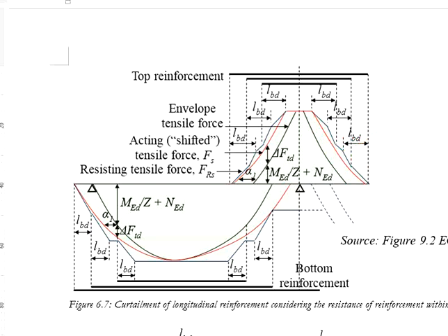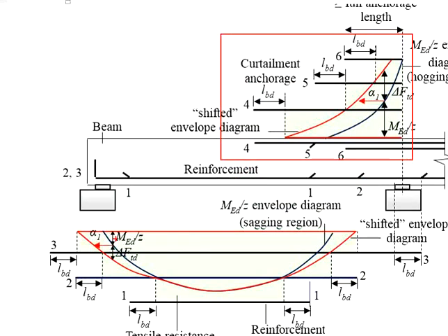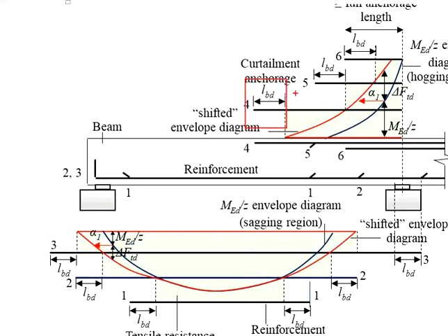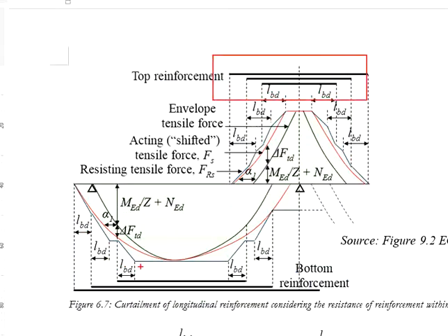You may choose to optimize this by minimizing the additional area here in order to maximize the saving of the materials. Now, if you are not that concerned about that limited amount of saving, probably you can simplify the model a bit, ending up with adopting this kind of model. The implication is that you are providing a slightly longer reinforcement bar as compared to those provided based on the model given by the Eurocode 2.